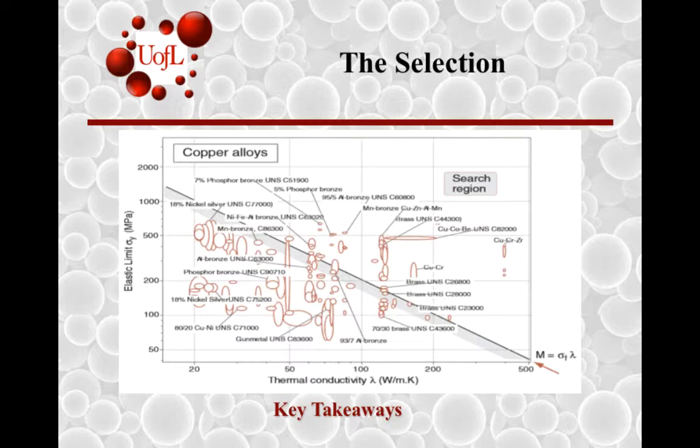And then the next would be phosphor bronze, which is around this area. And then you have the brass down here. It's not as conductive, but it's a little more resistant to corrosion, and the cost is just a tad more. But the most practical solution would be aluminum bronze, because the cost is in the middle, and it has decent conductivity and elastic limit, and aluminum's fairly light.